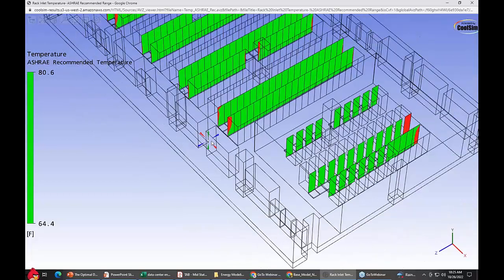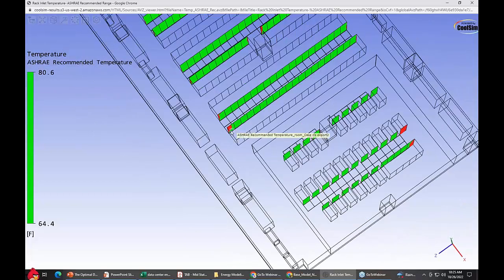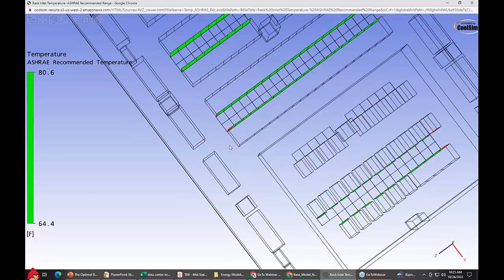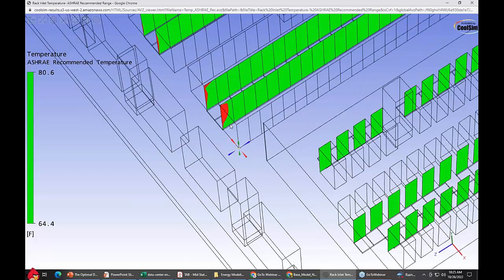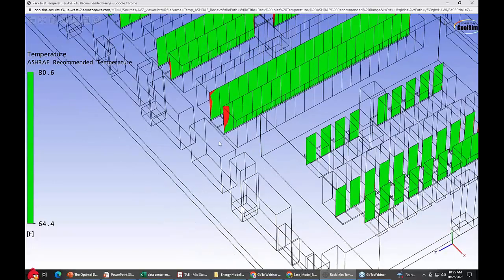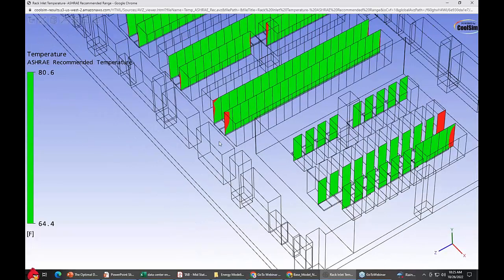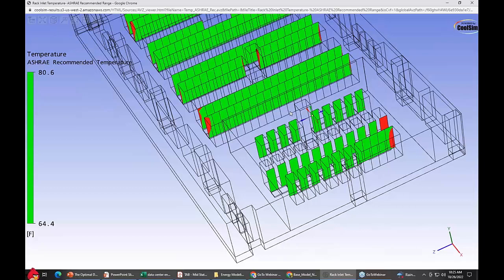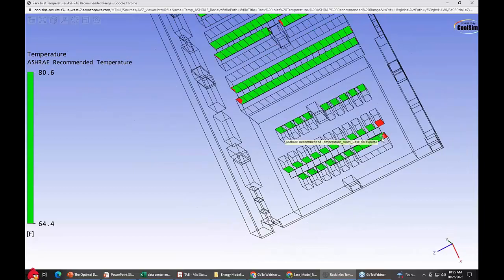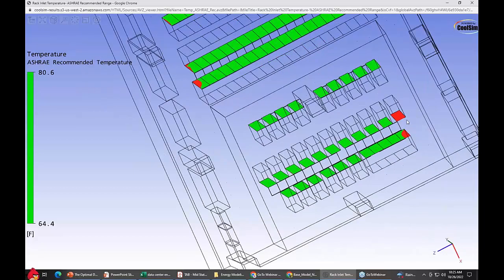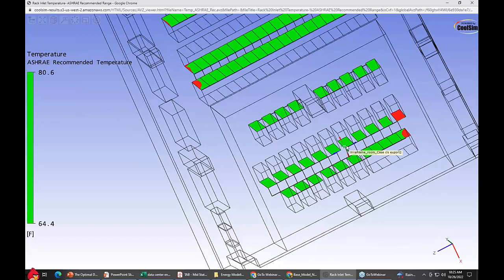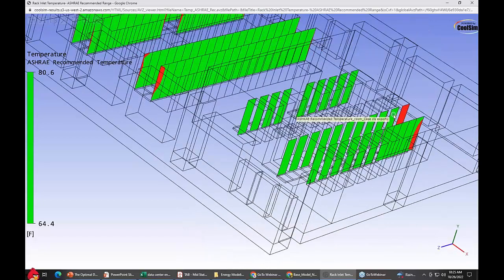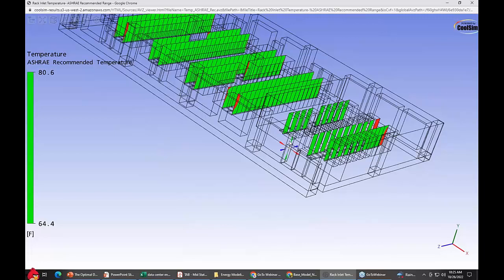It's getting a lot of velocity from the crack unit here under the floor, so the perforated tile is not performing really well right there due to high velocity underneath it, and Mr. Bernoulli is causing pressure to be low right there due to high velocity. And so edges are always problematic. Over here, you know, there's a tile missing, so there's that. You could fix this room a little better so that one doesn't pop out so badly. But in general, this one's optimized.